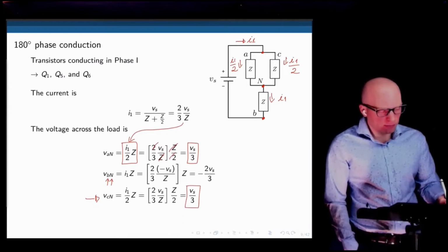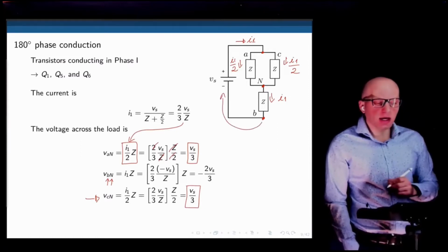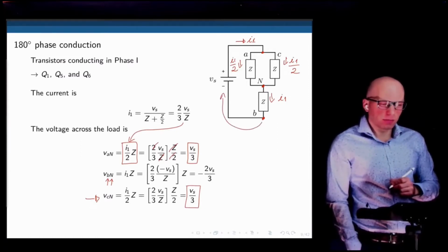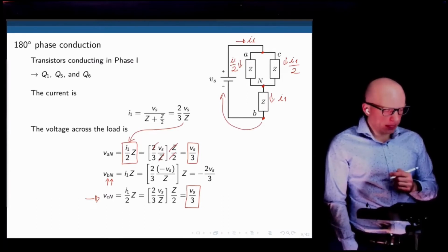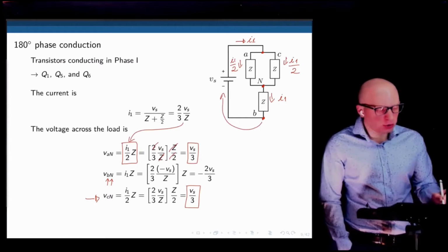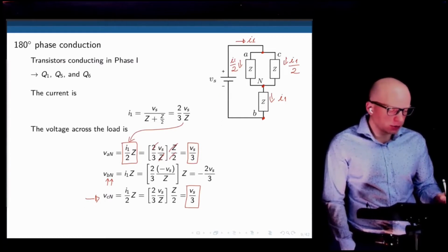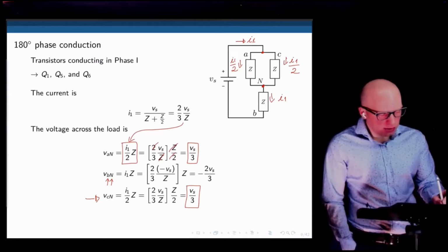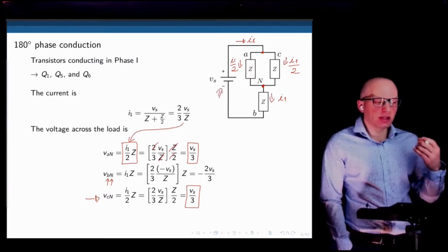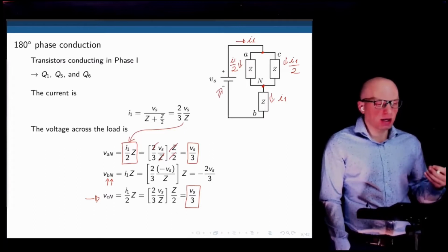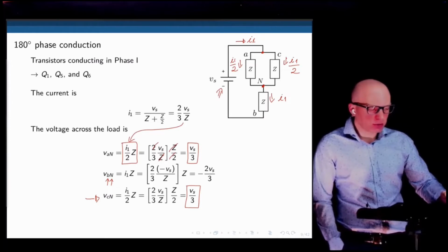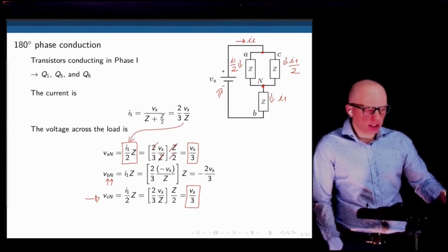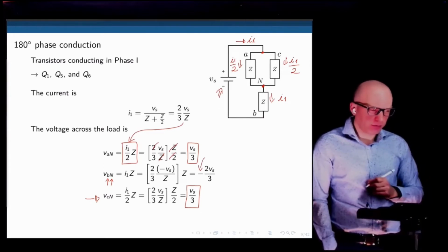It's 0, right? And the voltage across here is basically negative Vs, right? It's negative Vs. I shouldn't say it is Vs. The voltage there with respect to the neutral is subjected to the negative side of this voltage. It's not necessarily Vs, but it's negative because you're measuring the other way around. When you go from A to neutral, the voltage is positive, but when you go from B to neutral, the voltage is negative. Hence the negative sign here.